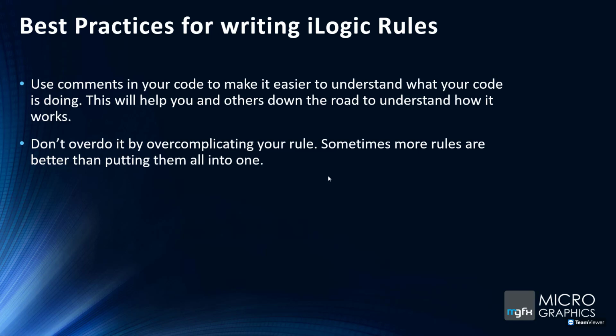If you get into iLogic, here are some best practices. You saw the gray text there when I put in the decal; those are comments. Use comments in your coding to see what's going on. You might be heavily into a project, then you need to go do something else. Even a day or two later, you come back and think, why did I do this? Why did I put this coding in? If you put lots of descriptions or comments in, it helps you, and it also helps others to see exactly why this was done.